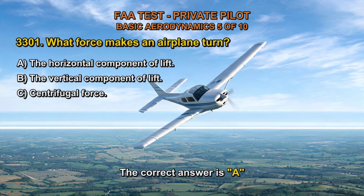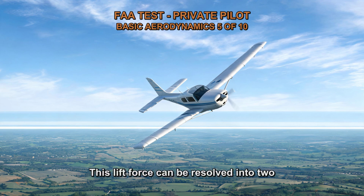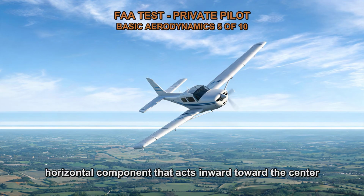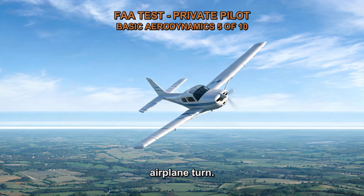The correct answer is A. The force that makes an airplane turn is the horizontal component of the lift. When an airplane is in a turn, the wings generate lift in a direction perpendicular to the wingspan. This lift force can be resolved into two components: a vertical component that opposes gravity and supports the weight of the aircraft, and a horizontal component that acts inward toward the center of the turn. It is this horizontal component of lift that provides the centripetal force necessary to make the airplane turn.